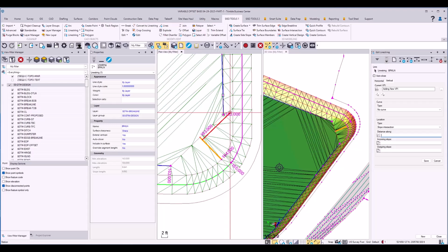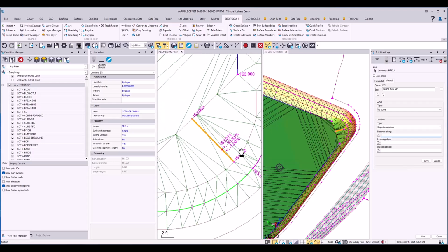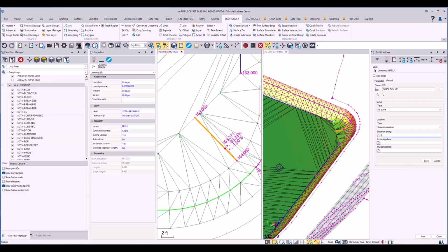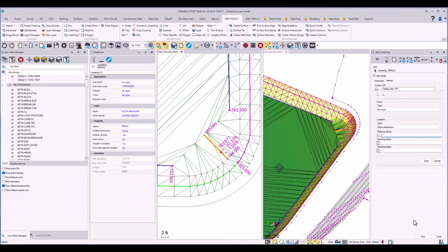Looking at how far we have off here and how far we have off here, this point is going to probably occur somewhere along in this. I'm giving it an approximate location. And then I want to go down at a negative 3:1 ratio, and then continue at a negative 1% to the end of the line. If I hit the save button, there is the information, and that's the location. It was pretty close to where I eyeballed it.